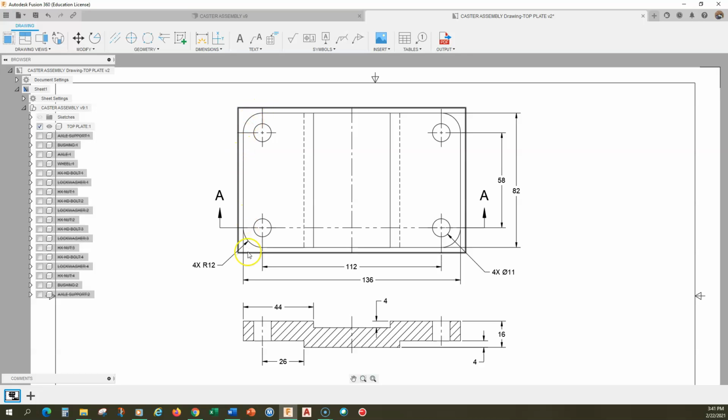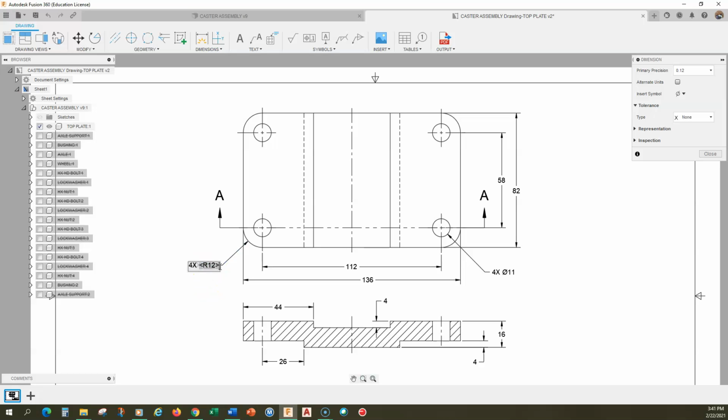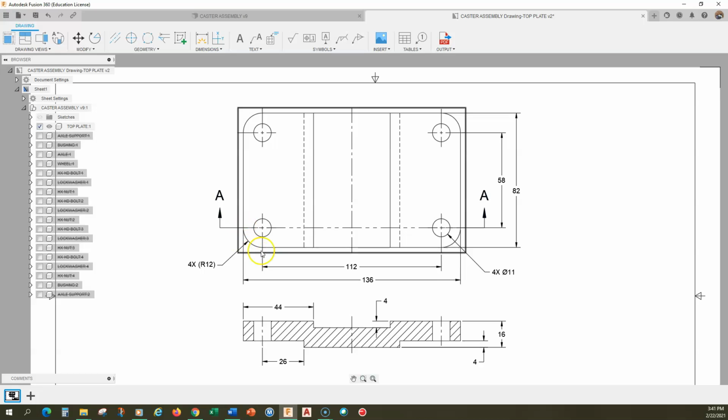So to really alleviate this issue, the outside curves here, these radii, again, they're not really functional. They're for appearance only. Okay. So what I'm going to do is put these in parentheses, right? And parentheses means that they're reference dimensions. That means that they're not going to have tolerances, okay? So it really tells the machinist that these are dimensions that are not super critical. And that's how we avoid this over-dimensioning. Notice that it would also be over-dimensioned on the depth as well.